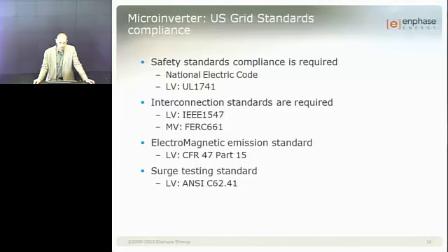So why would we do this? Well, the beauty of a three-phase system is that you don't need to circulate a neutral current for nothing. In a three-phase system, you basically don't need the neutral if everything is balanced. So you eliminate the return loss. You inject power on all three phases, and the return magically disappears. So you don't have any losses in the return, which means that it's basically half the line loss on the copper system.